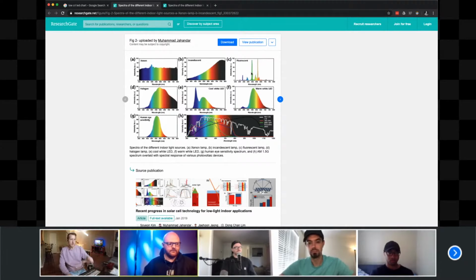And so when you buy LED fixtures, you really want to consider CRI, or there are other metrics that help measure how accurate the color is when it's seen on camera. But CRI is definitely one of the more popular ones. When you see a fixture that's super cheap but has a CRI of 75, you probably want to avoid that one, especially if you're doing stuff for a camera. But a higher CRI fixture might be just fine, and as long as you consider all those other factors you mentioned, might be a good option for you.